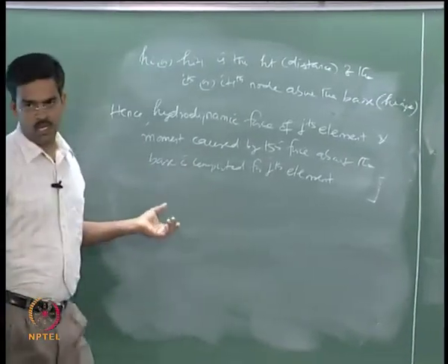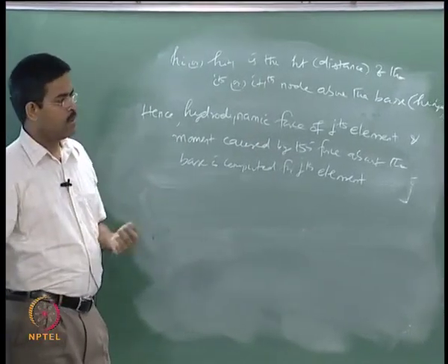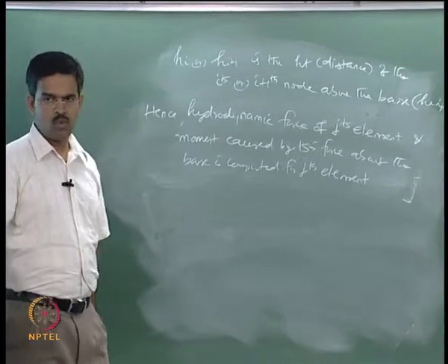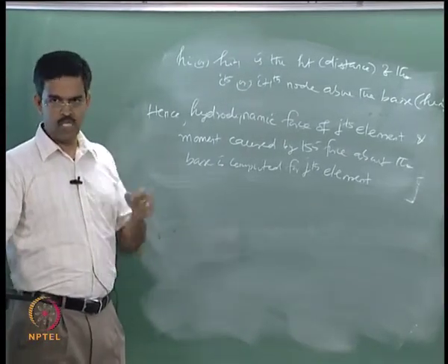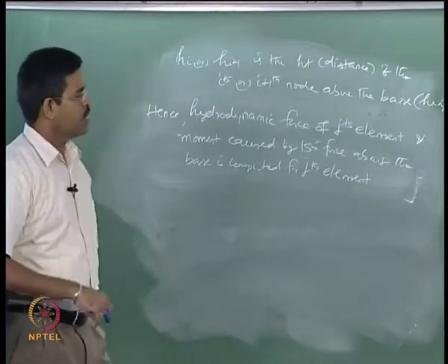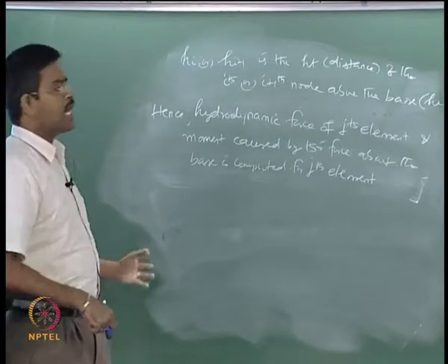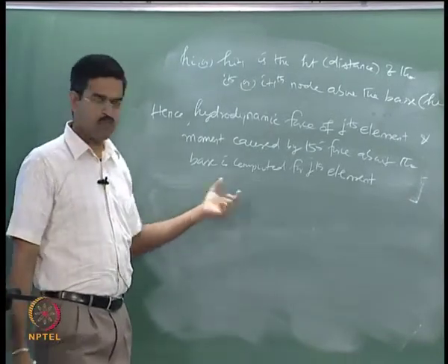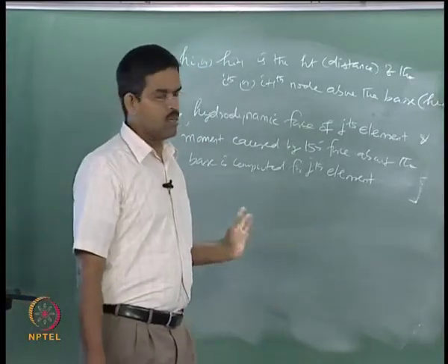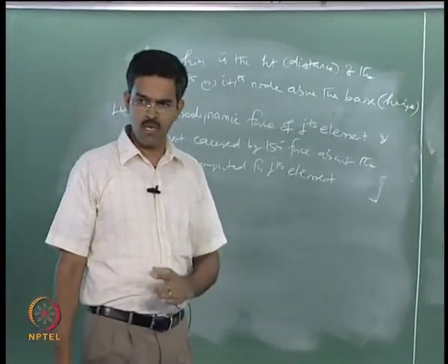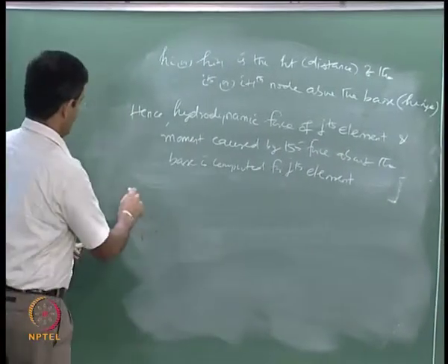For the hydrodynamic part, I will again subdivide the portion below the still water level into a number of nodes, and find the water particle velocity at the respective nodes and the distances of those nodes from the base. Keep on adding them, I will get the moments. So, f of t can be easily obtained for the entire tower, which comprises lateral loading caused by hydrodynamic and aerodynamic forces. Now, the interesting part here is there is an observation.